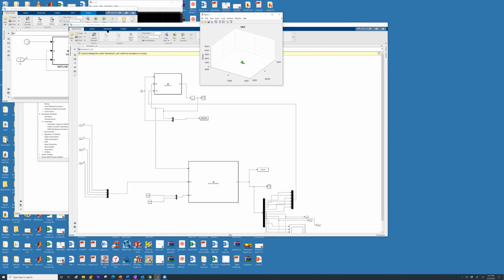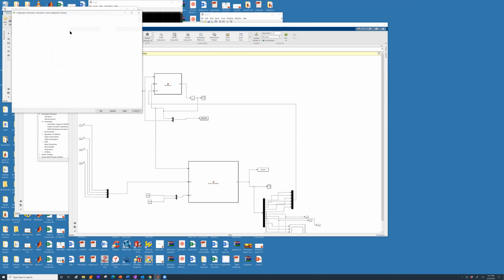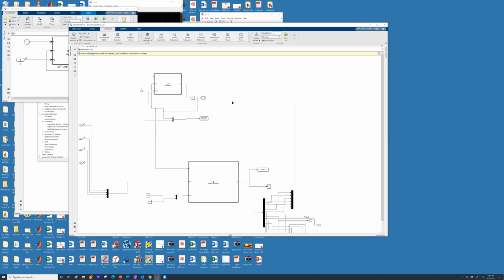If your code is not running, then the only reason for that is you go to modeling, go to model settings, and your MATLAB is trying to access variables that are not in the workspace. So unclick input and initial state. Okay, next part is super duper important. So I'm going to take a minute just to make sure that everyone has this code in front of them running. And just tell me if your code is running or not.